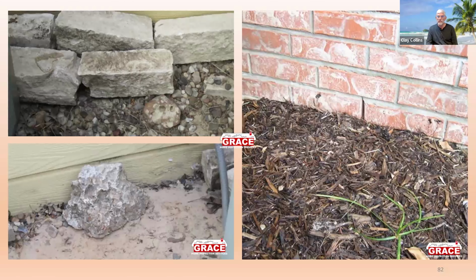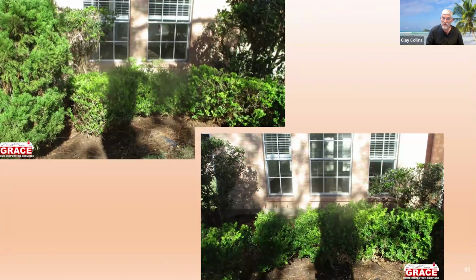I'm sure we've all seen when you come into a home where the agent told them, do some landscaping to improve the yard, to improve the curb appeal. And you walk up and they have added way too much mulch and it covers all the weep holes. I put this in grading and drainage because that has an impact on your soil. It has an impact on the drainage.